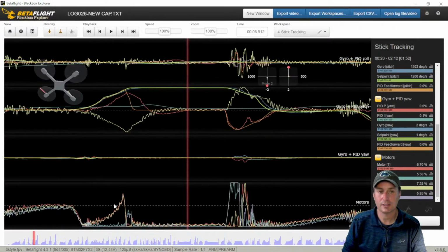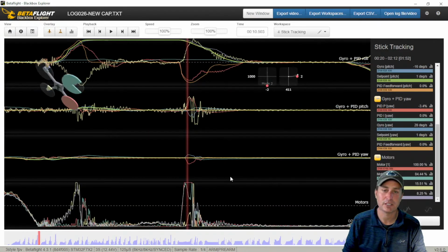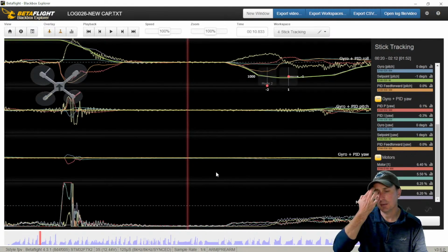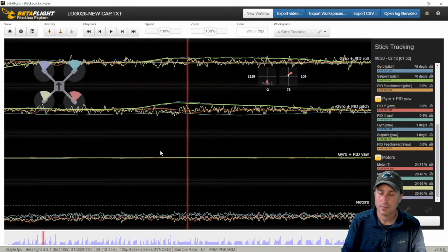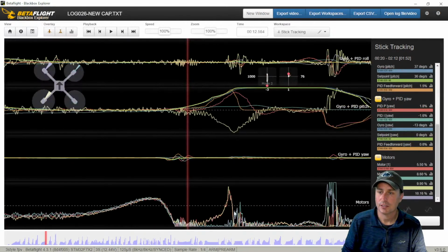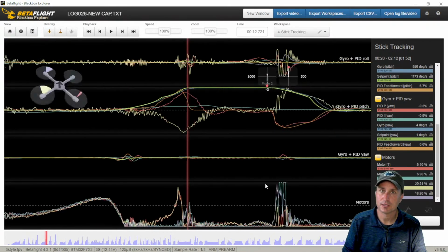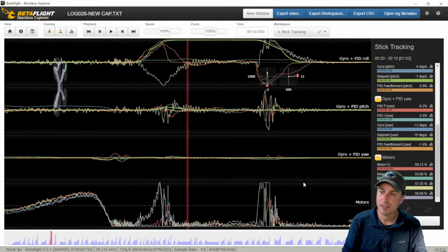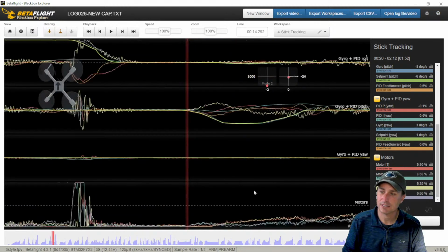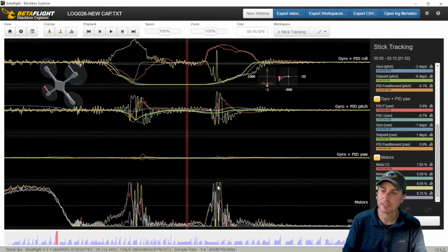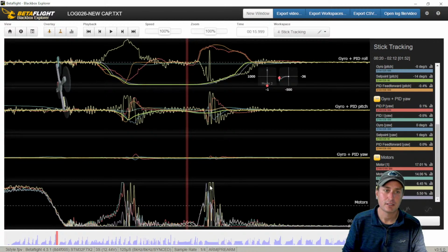It seemed to me like this up front here was a little bit better with the more name brand capacitor. The capacitor he had on there was just the one that came with it, which is kind of like an unbranded silver looking thing. I had Panasonic ones. So you could see the upfront moves here seemed a little bit better to me. But the back end, you can still see the electrical noise. It's not so bad, like that one's hardly there at all. Here you can see it. Like you shouldn't have these up and down spikes here.